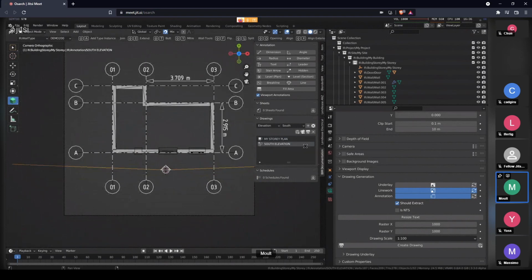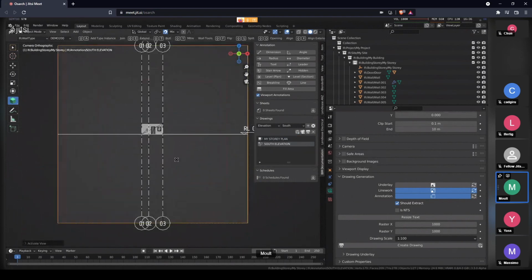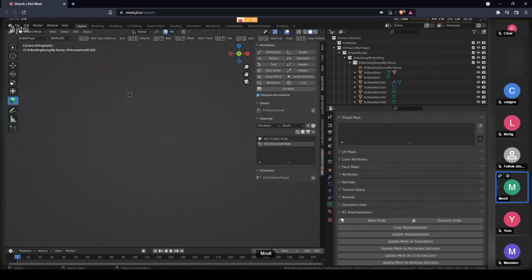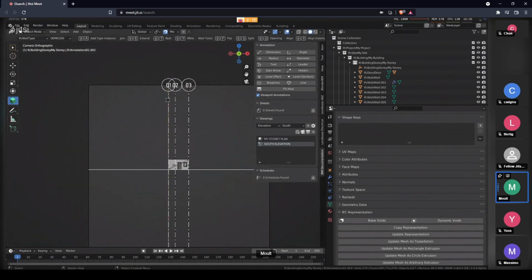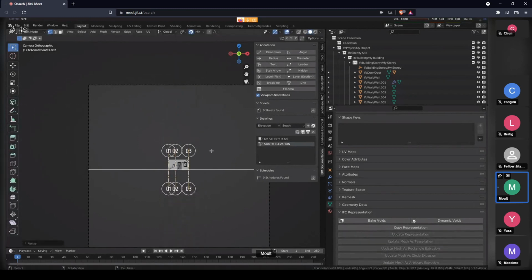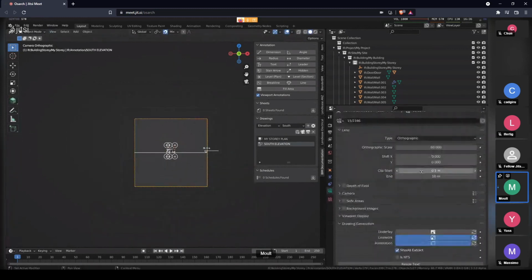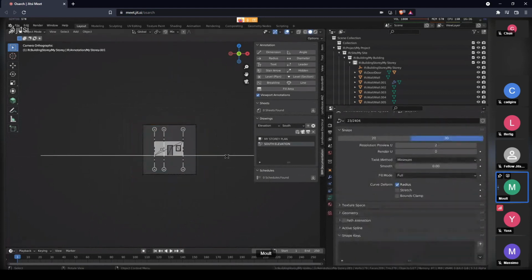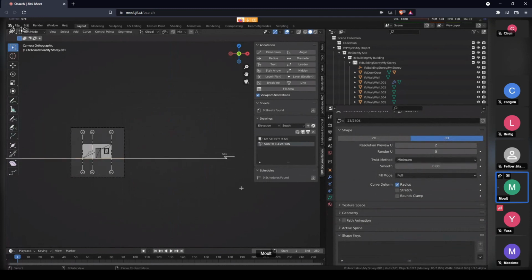And I'll jump into my elevation view. You can see my elevation has also auto-generated the grid annotations. Oops, my scroll bar went crazy there. It knows that for elevations, annotations go up the page. So I can just go and scale that down. There we go. We'll just resize it to my building. Or I could have just scaled my drawing. That's more sensible. So let's make that up to my drawing extents, and we'll take the auto-generated level marker and scale that down as well.